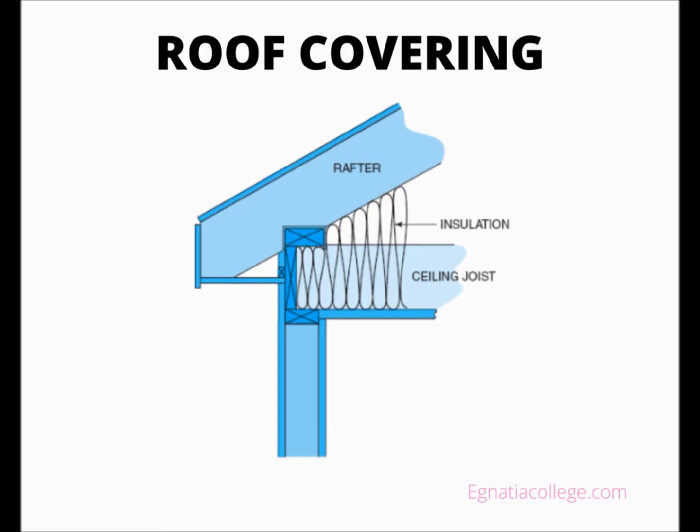Asphalt roofing materials, including felt and shingles, are sold by their weight per 100 square feet of coverage. 100 square feet of roof is called a square. If enough shingles to cover 1 square weigh 235 pounds, they are called 235-pound shingles. Asphalt saturated felt underlayment is typically 15 pounds or 30 pounds weight.